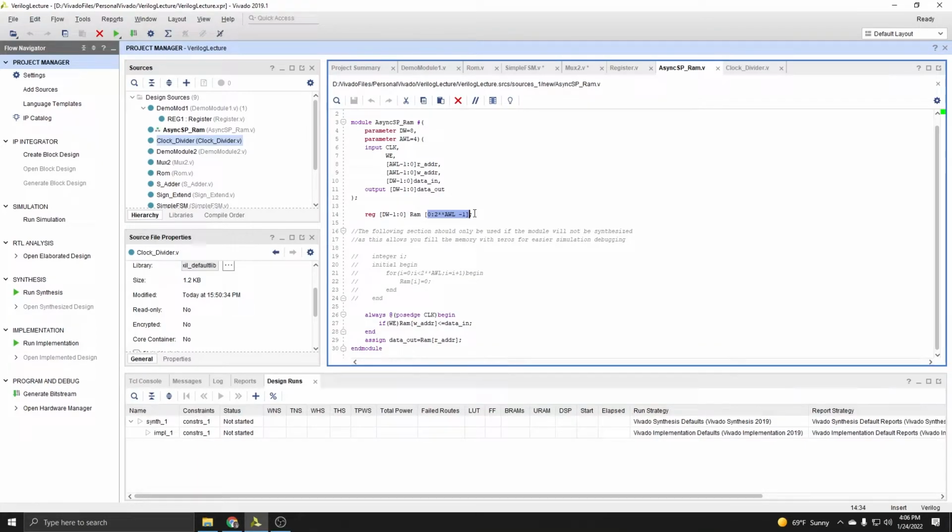large, because your FPGA, which is what the tool is always trying to cater to, has a limited number of resources. You can't put, for example, a 32-bit address width, even though that's technically what a MIPS processor uses, because that's more than is going to be on any FPGA that you buy for a reasonable price. So just keep in mind your address word size, because it would absolutely give you an error in Vivado when you tried to simulate. If you did 2 to the 32, you'd have a massive issue.